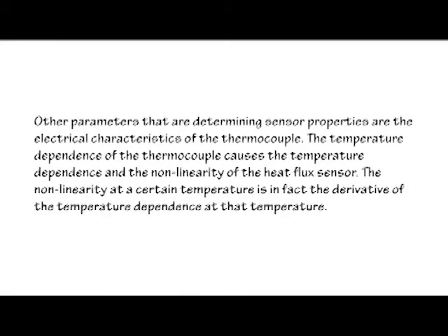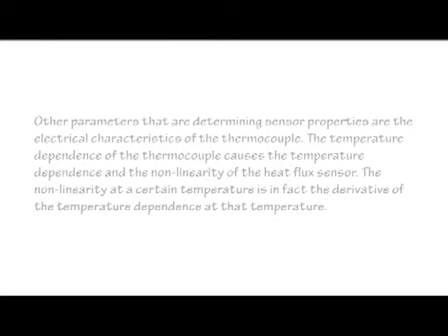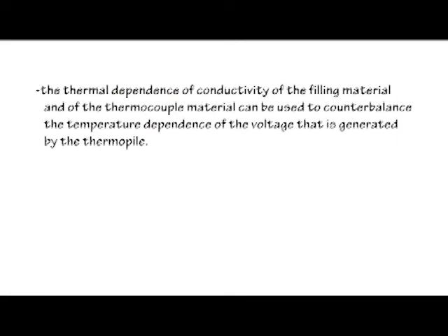The temperature dependence of the thermocouple causes the temperature dependence and the nonlinearity of the heat flux sensor. The nonlinearity at a certain temperature is in fact the derivative of the temperature dependence at that temperature. However, a well-designed sensor may have a lower temperature dependence and better linearity than expected. There are two ways of achieving this. First is that the thermal dependence of conductivity of the filling material and of the thermocouple material can be used to counterbalance the temperature dependence of the voltage that is generated by the thermopile.